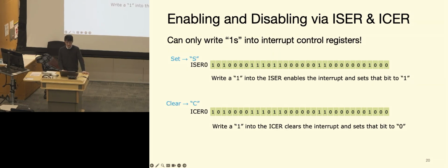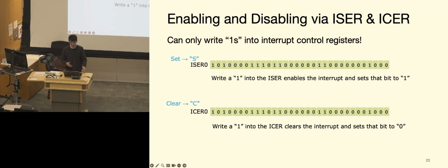The second is essentially providing another layer of protection, or another layer of redundancy, because these are quite important. If, say, some hardware got stuck inside of the enables and it's always set there, the program might have trouble accessing that or writing a value to that register. So we have additional registers, the clear registers, that make sure that every time this command happens, it's executed at the hardware level.